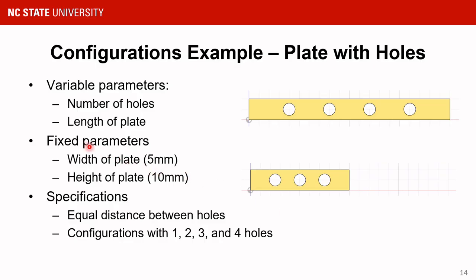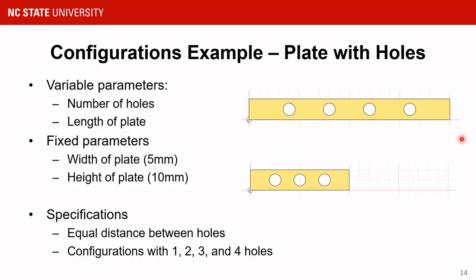One additional parameter that I'm actually going to add is the hole diameter. The hole diameter is going to be half of the height. So these are fixed parameters. This is a variable parameter, just like we saw in one of the earlier slides if we're looking at some sort of function between dimensions. Okay, so this is the sort of formula that we're going to use to create this part. I'm going to switch over to Fusion now, and we'll take a look at how to do that.